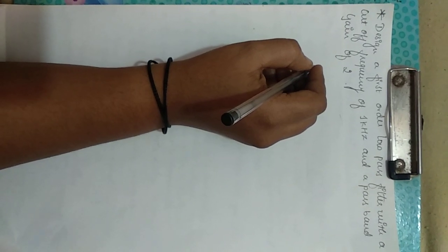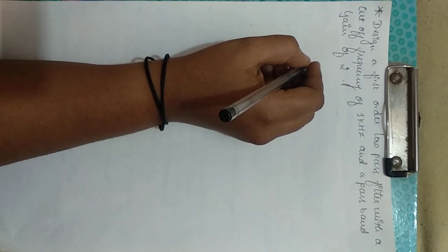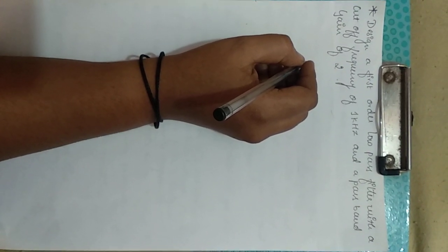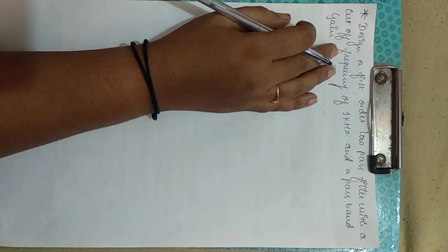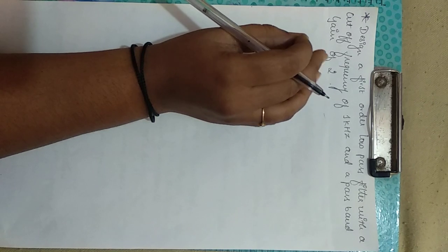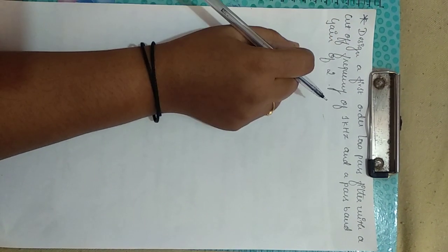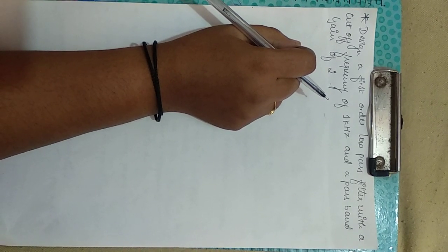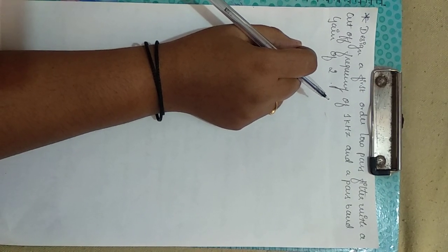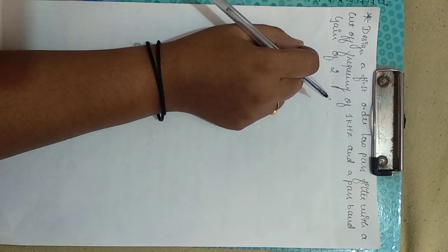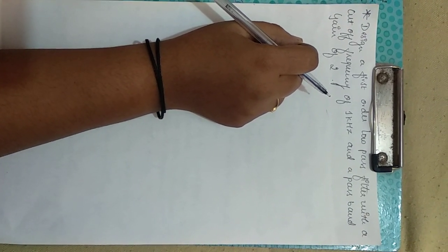Before we solve the problems on the first order low pass Butterworth filter, we have to know what frequency scaling is. Frequency scaling is nothing but, once the filter is designed, sometimes it is necessary to change the value of the cutoff frequency FH. The method used to change your original cutoff frequency FH to a new cutoff frequency FH1 is called frequency scaling.